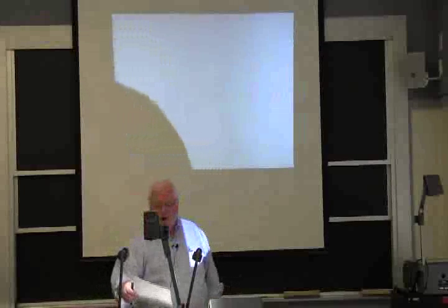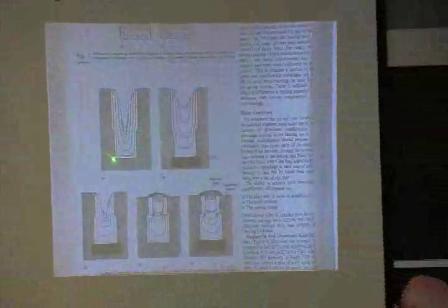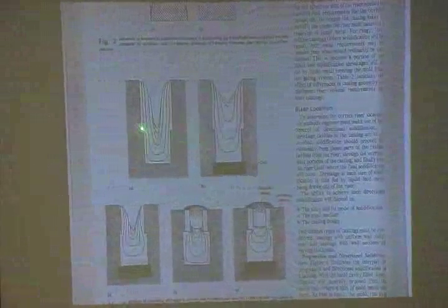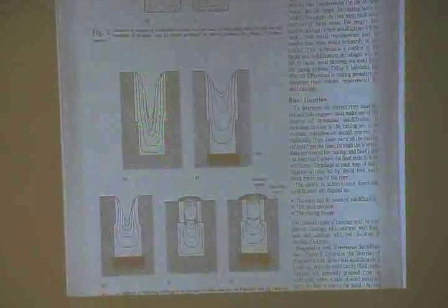So in casting, we talked about continuous casting, and I may talk about a couple of those, but in general, we're trying to impart some sort of shape. And we've got this problem of shrinkage over here, and this shows a casting. Just to cast a part like this, you may have to have a mold that's 3 times as high if you just cast the thing into a sand mold.